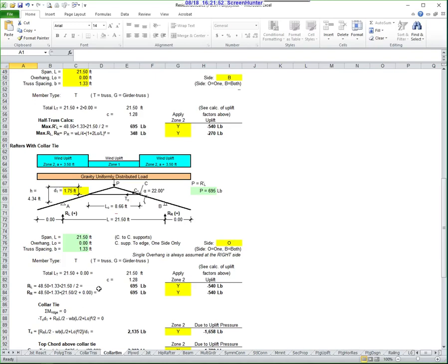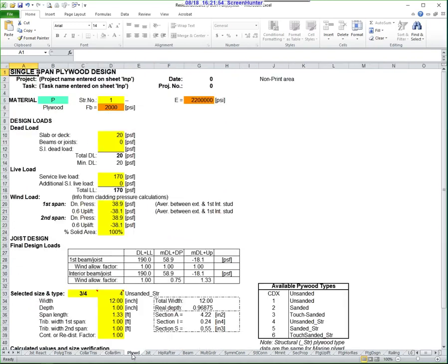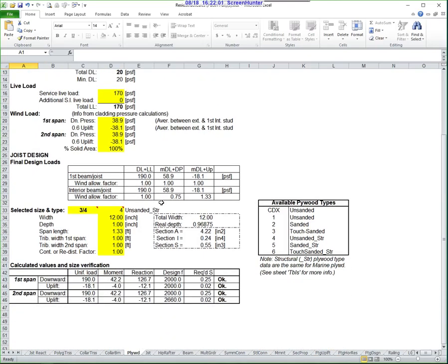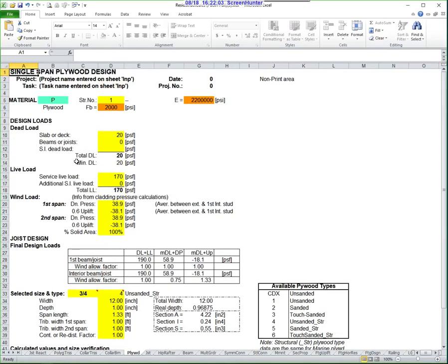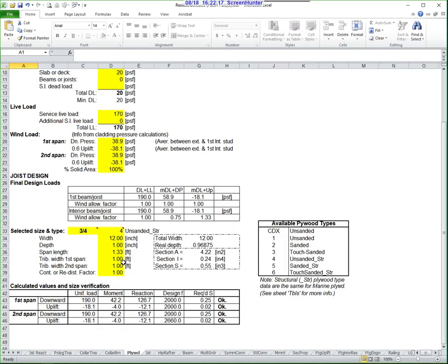Ply WD, Plywood Design and Verifications. This design module calculates plywood stresses and forces under out-of-plane loads only. It is not for diaphragm calculations. It uses dimensions provided by the APA, American Plywood Association, for fibers oriented longitudinally or transversely.